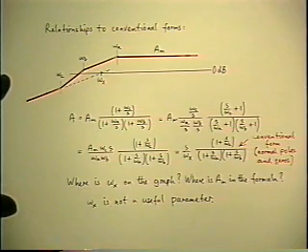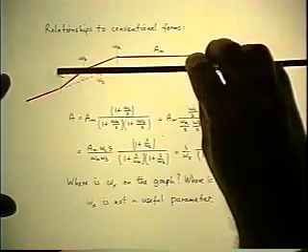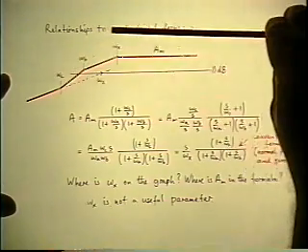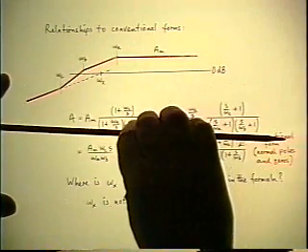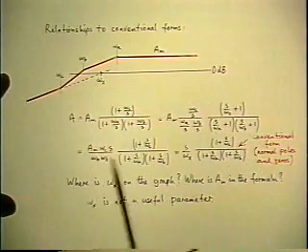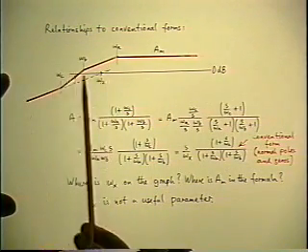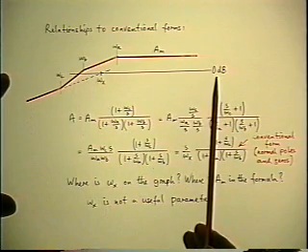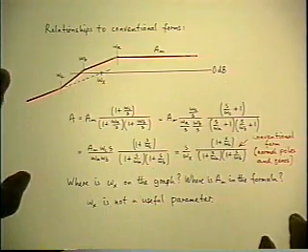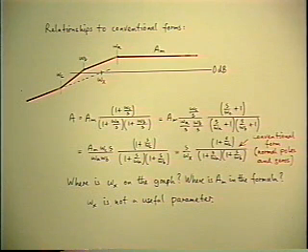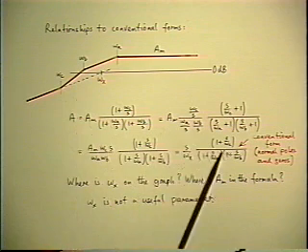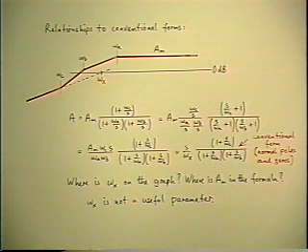Now, without knowing numbers, I don't know where to put that line. It could be up here, could be down there, but wherever it is, omega x is the frequency where the zero frequency asymptote crosses the 0 dB axis. Well, that's okay, but who cares? It's not an important or useful parameter of the problem.